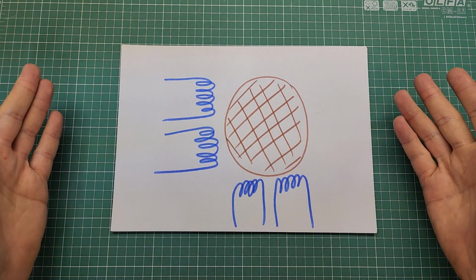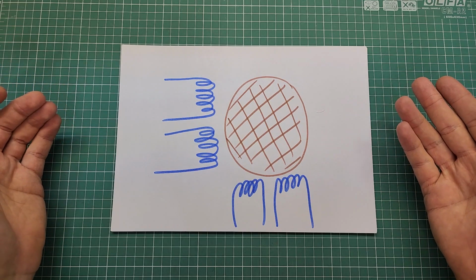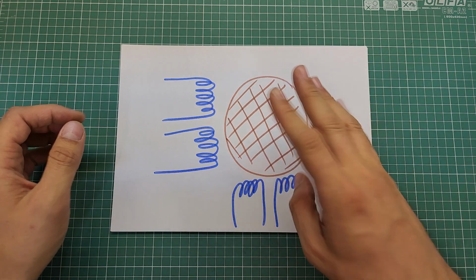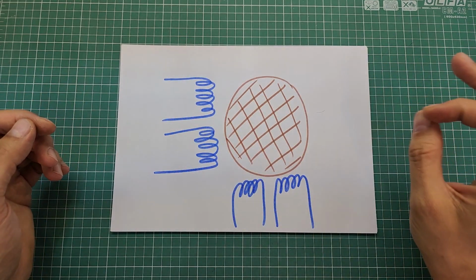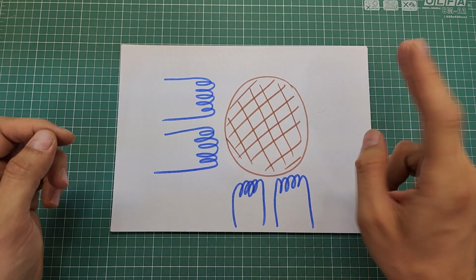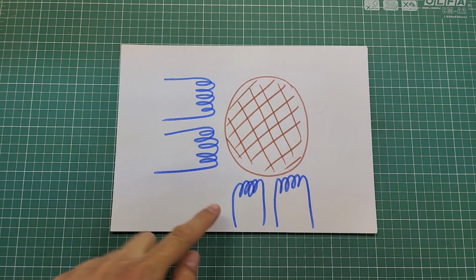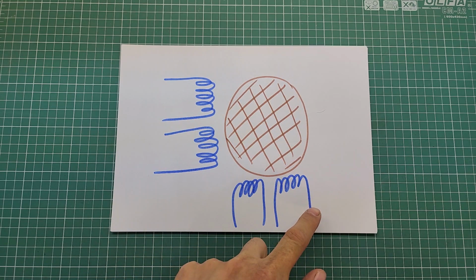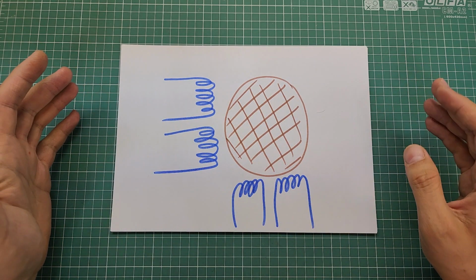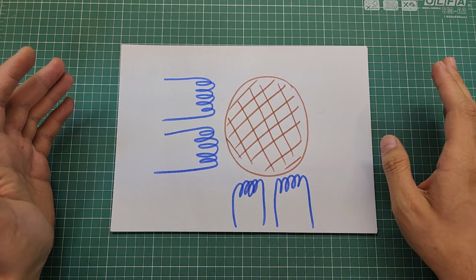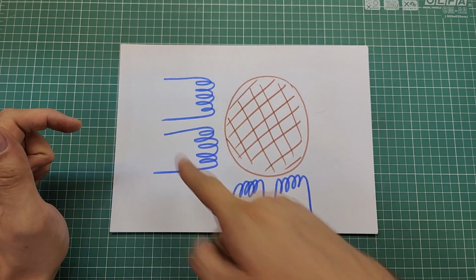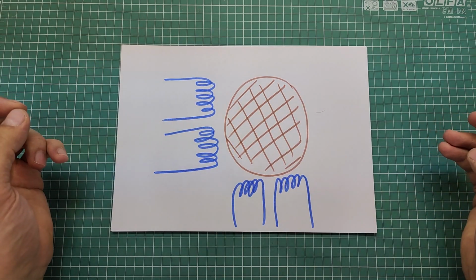Inside any ordinary stepper motor, there are some windings, actually 4 windings like these. Each of the windings has 2 ends. Then here you can see 8 ends: 1, 2, 3, 4, 5, 6, 7 and 8. If you face a stepper motor that has 8 wires, it means that these winding ends are pulled out directly.